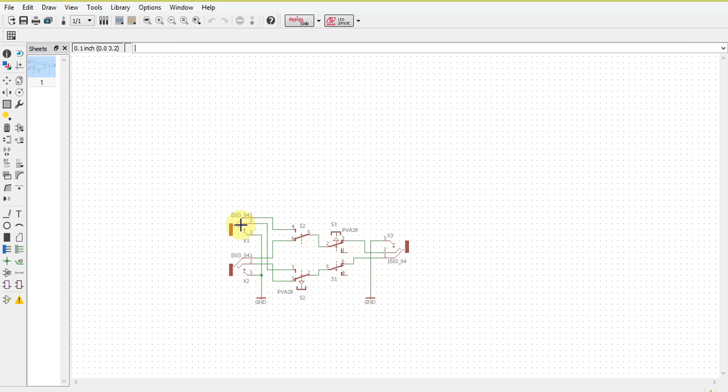So I have two input jacks here. And then I have a double pole, double throw switch. I need to be able to switch left and right channels, that's why I have a double pole, double throw switch. When I have the switch in positions 4 and 1, for example, then I have the left and right channels selected from jack 1, which is X1 in this representation. And if I have the switch in the other position, which is 6 and 3, then I've selected the audio left and right channels from X2, the second input.